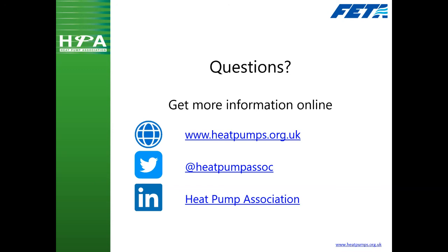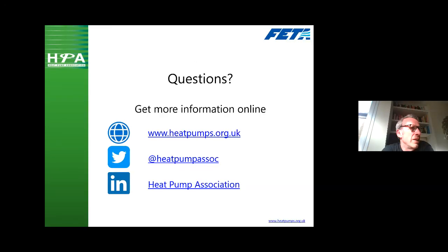Shall I go? You know, Craig, yep. Yeah. Well, from our point of view, we work on a life cycle of 15 years for an air source heat pump. We do recommend that it's serviced annually, but unlike a gas boiler, it's not a legal obligation. It's just to ensure that you extend the life of that unit for as long as possible, and ensure the operation. So yeah, that's from a Daikin perspective.